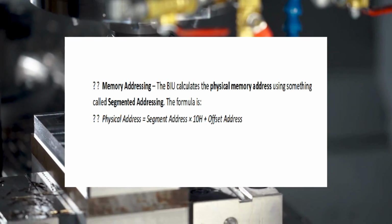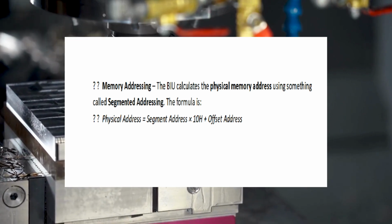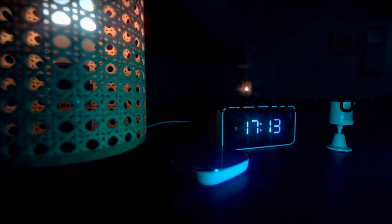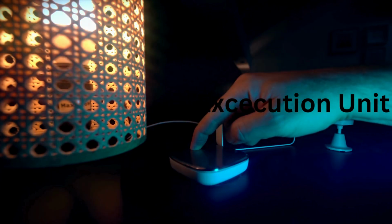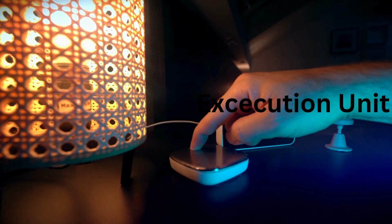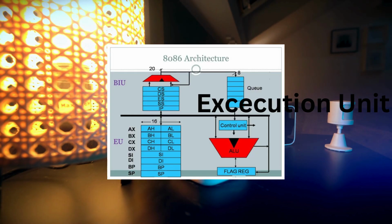CS, code segment, holds the program code. DS, data segment, holds program data. SS, stack segment, manages function calls and stack operations. ES, extra segment, used for additional data. Let me show you how segmentation works. This technique allowed the 8086 to access a whopping 1 megabyte of memory, which was huge back then.